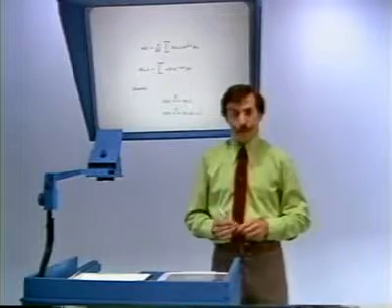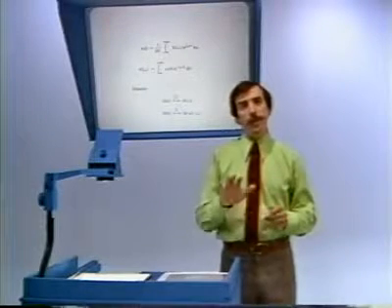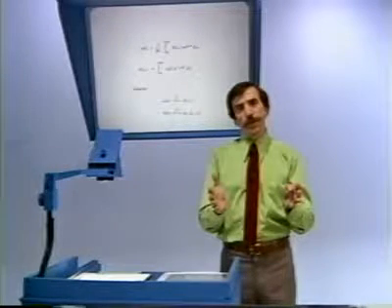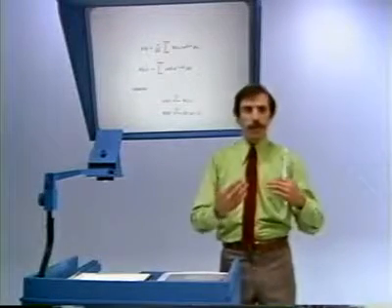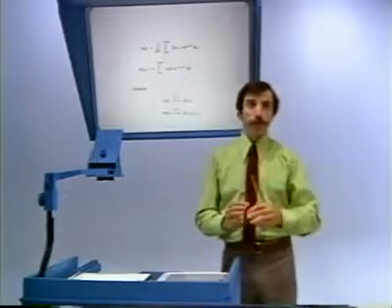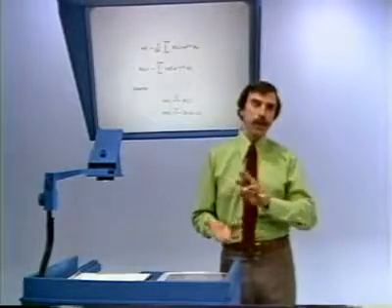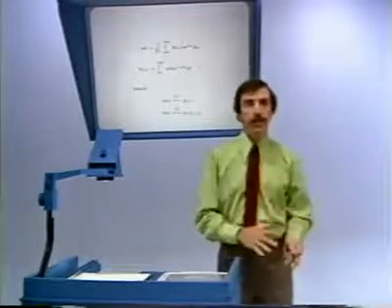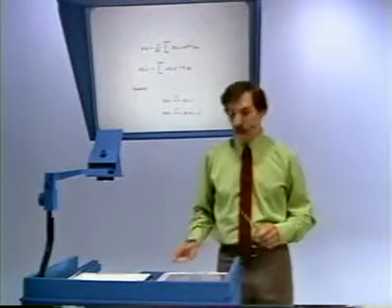It's very useful. It, by the way, is not a duality that surfaced in the Fourier series because, as you recall, the Fourier series begins with a continuous time function and in the frequency domain generates a sequence, which would just naturally have problems associated with it if we attempted to interpret a duality. And we'll see also that in the discrete time case, one of the important differences between continuous time and discrete time Fourier transforms is the fact that in continuous time we have duality, in discrete time, in the discrete time Fourier transform we don't.